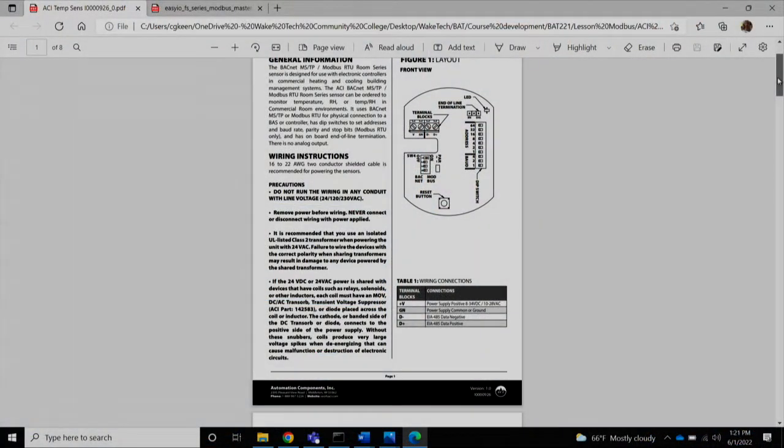So for this one, they have to figure out how to hook up power. The end of line termination here is a jumper that they can set. We have covered binary, so the fact that the address is done here with a binary dip switch is something they should be able to do, right? Be able to figure out what the actual number is. But be careful of the details. The least significant bit is not the top bit. It's in between here, right?